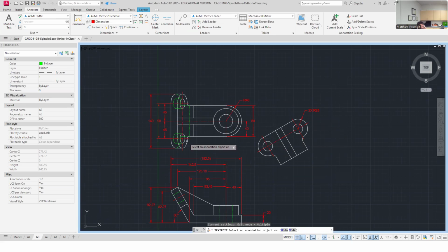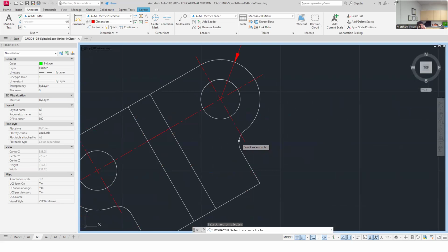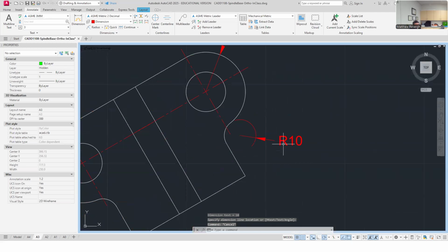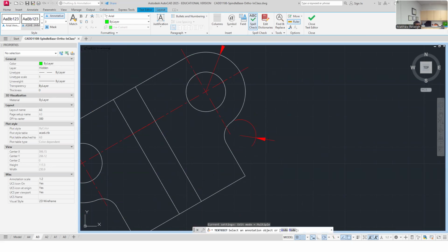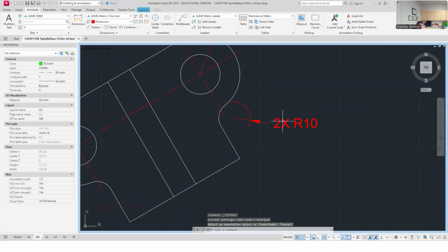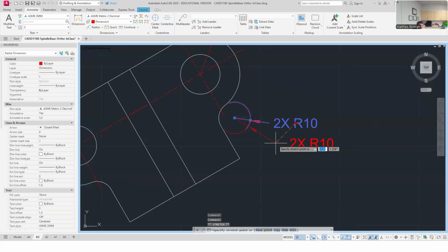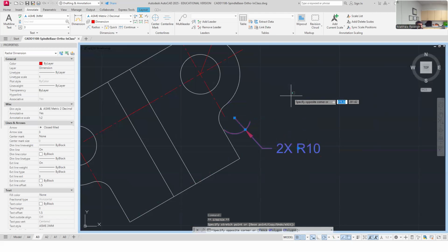And then it's got that complicated feature where they transition back to the 80 millimeter versus where it comes out to this ear. So I need to include that radius, this thing here. I can drop this in anywhere that'll work good. Sure, that'll kind of show me a weird radius. That's good. And there's two of those, so I'm gonna drop in a 2x by those as well. It's a 2x radius. Maybe I'll drop this a little low and keep my leader line just a little bit more on the angle side, like that, maybe.